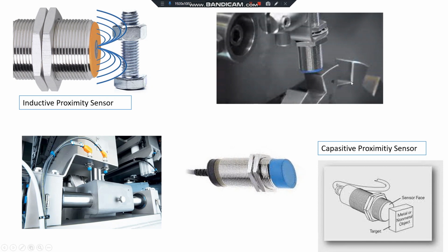And when the downside comes in front of the proximity sensor, it is not activated and does not send any signal. In this way, up, down, activated, not activated, activated, the PLC will count the turns of this machine, and can use this information for many aims.